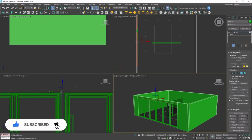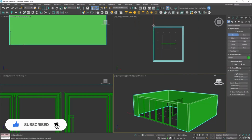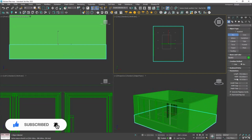And now let's create some floors. So I'm going to turn off our polygon select tool, go to the Create tab and select Box, and in the top view, we can click and drag, and that's going to snap to our walls. And then rather than pulling it up, I'm actually going to pull it down, and let's change the height to -10 centimeters.